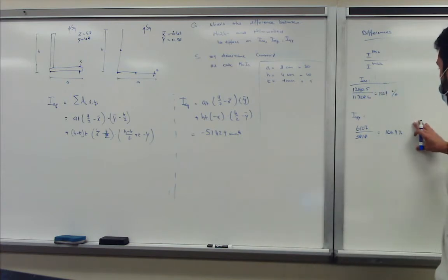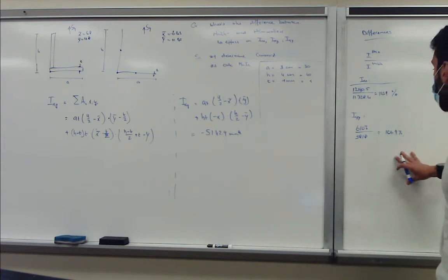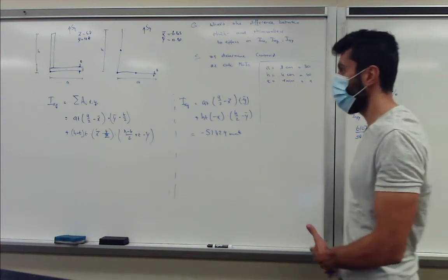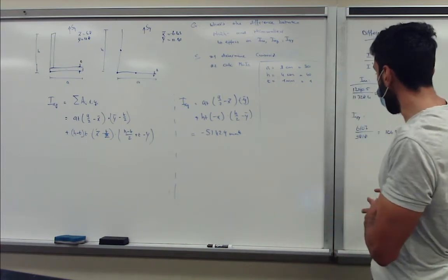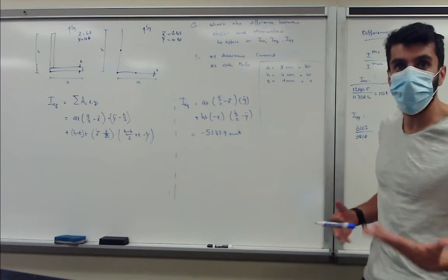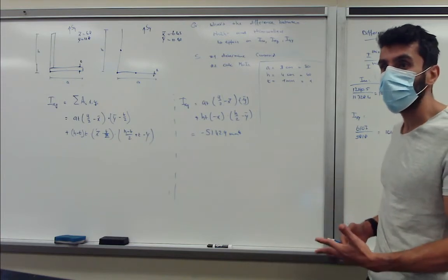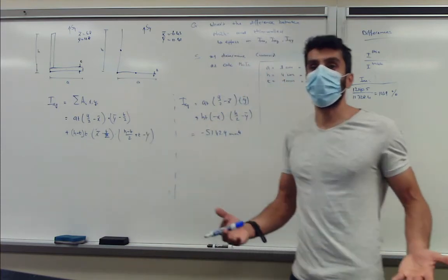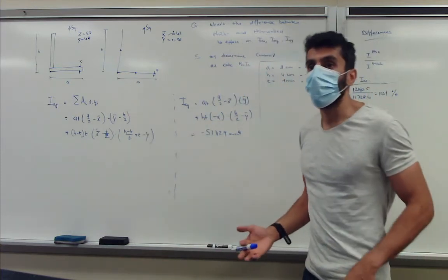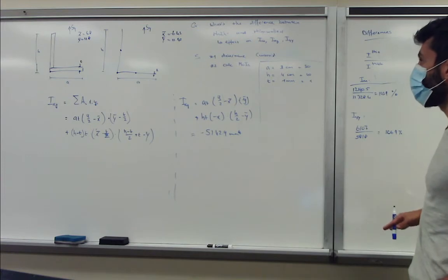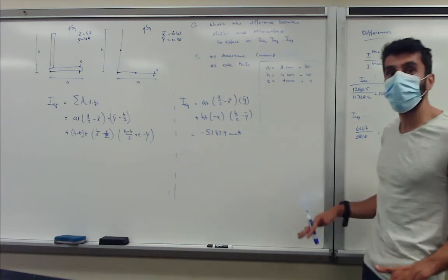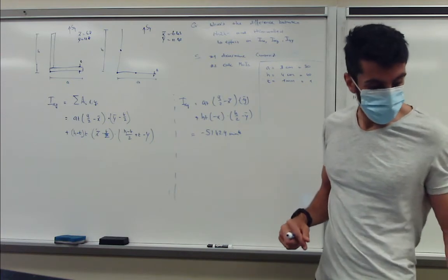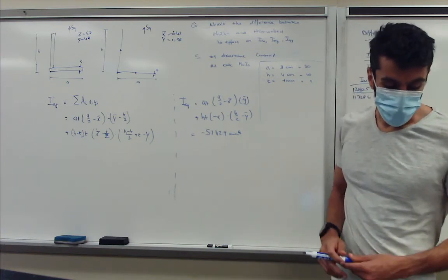So in this case, you can make the justification saying it's below 5%, therefore I ignore it. But if you, as an engineer, decide it's my marker, I'm going to set it at 1%, therefore it's higher than 1%, therefore I can continue calculating the shear flows using thick wall, still would be a valid solution. But in this case, I would always go for the fact if you can ignore it, because it just makes your life simpler. And then you can go and calculate